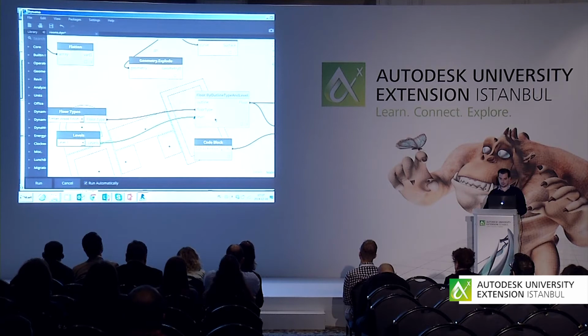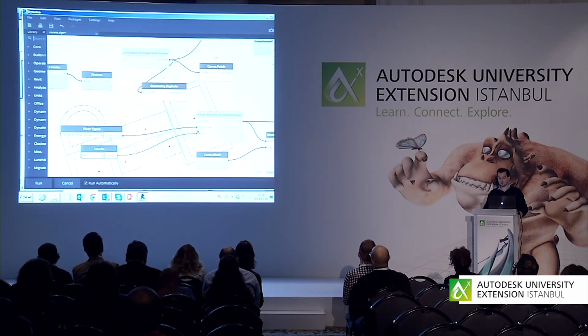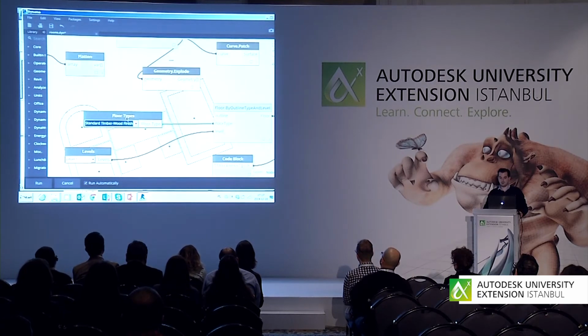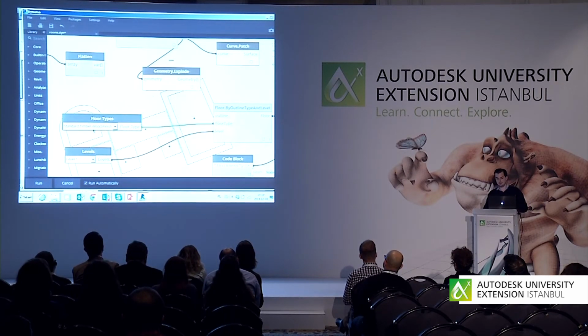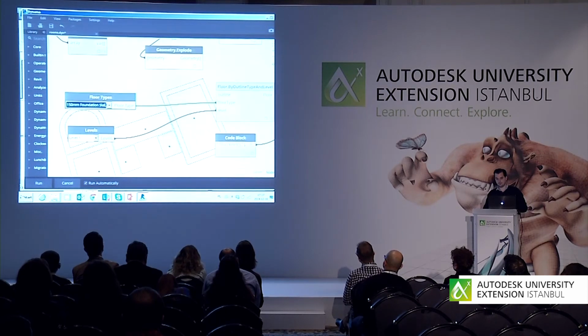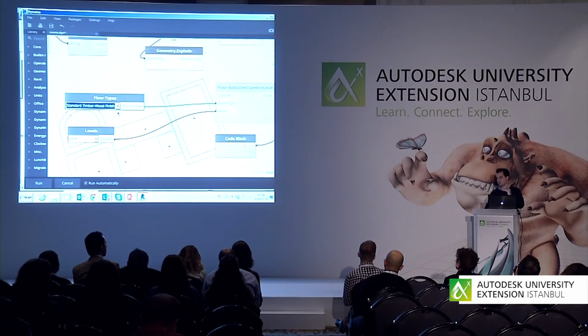And what you have to do is just say the outline, so the curves defining the floor, and the type of floors. Once you open your Revit template file and use this node, it will also look into your template file and you will see the list of available floors that you have in your starting file.